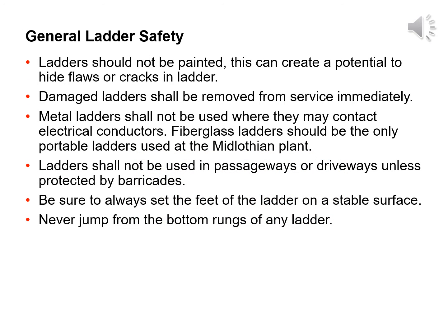Portable ladders should not be painted. This can create a potential to hide flaws or cracks in a ladder. Metal ladders shall not be used where they may contact electrical conductors. Fiberglass ladders should be the only portable ladders used at the Midlothian plant. Ladders should never be used in passageways, doorways, or driveways unless protected by barricades.